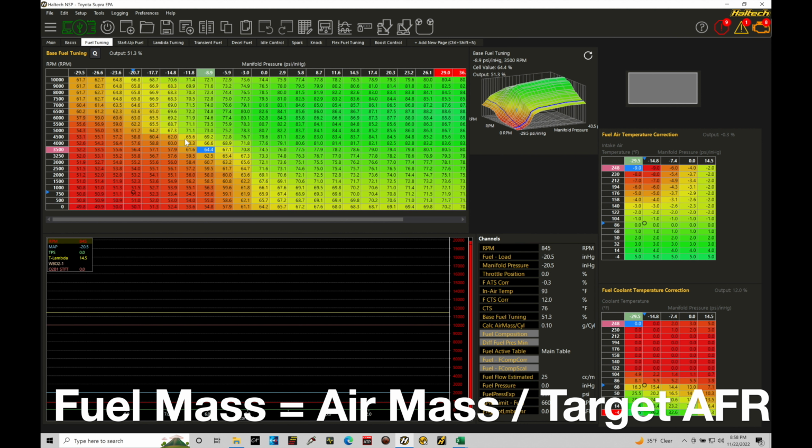Because we have to account for that density, because it can affect how much fuel we need to deliver to the engine, because the engine's going to burn more or less oxygen depending on what the density is going to be, we have something called air mass. So air mass allows us to correct for both the volume flow and the amount of oxygen molecules that the engine is ingesting, that density portion. And that's where we get our air mass. Fuel mass is going to be the same thing. We can account for the volume flow of fuel that we need to bring into the engine, also the density of the fuel based on the type of fuel we're dealing with. Petrol, ethanol, methanol all have different fuel densities, so we want to account for that. And that's a whole other topic that we're not going to cover right now. But just understanding the concept here of air mass or fuel mass, it's volume times density.